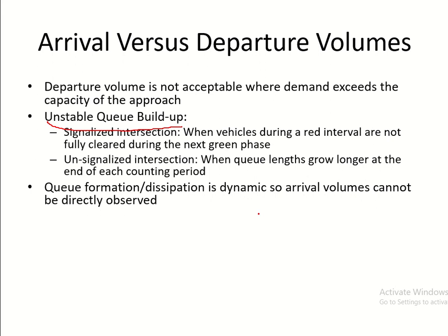Moving backward meaning what? Vehicles are adding to the back of the queue. So the queue was up to this point, the signal became red, now more vehicles are adding to the queue, so the queue is moving backward now. This is the end of the queue now, and the end of the queue will keep on going in this direction until these vehicles have a chance to move. So when vehicles have a chance to move, the queue moves forward, and when the vehicles don't have a chance to move because of other traffic or because of the red signal, the queue moves backward. So if you try to count the number of vehicles in the queue, the arrival volume, then you will keep on jogging forward and backward. Yeah? Somebody would think that you are doing exercise, you are jogging, or getting ready for the Olympics or something. Okay, this is not the case. So it's very difficult to count the arrival volume.